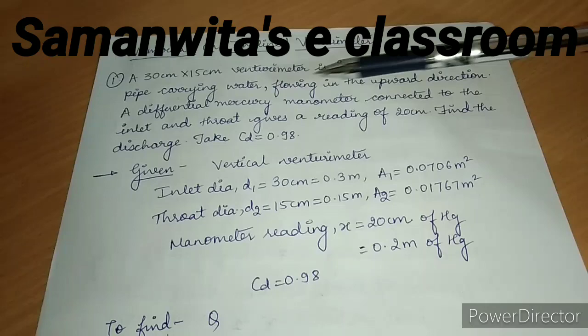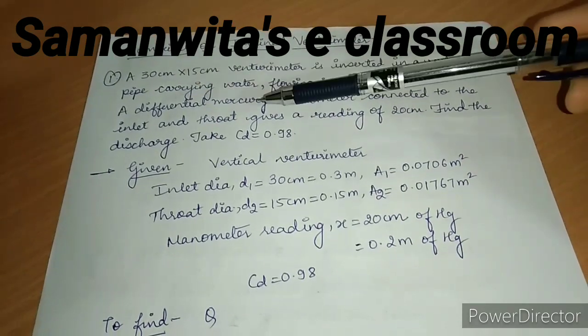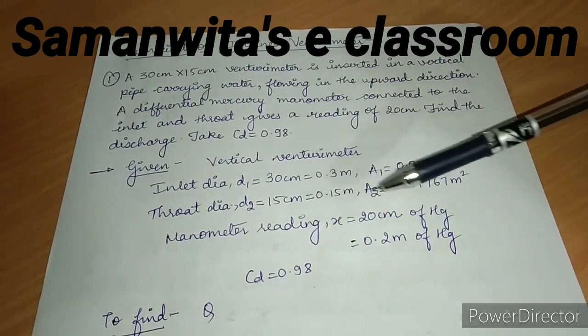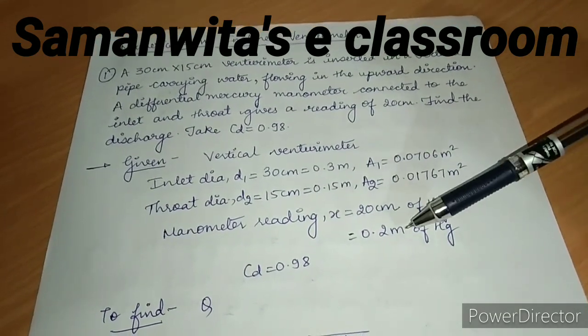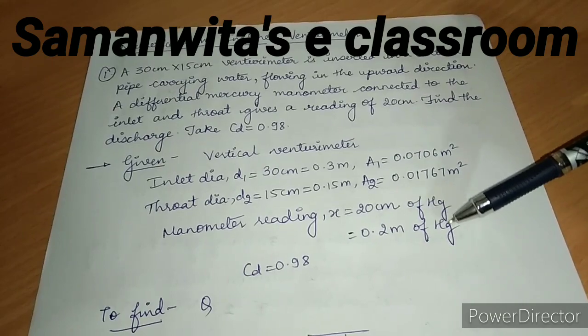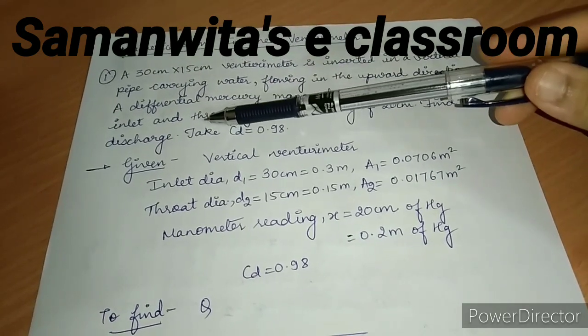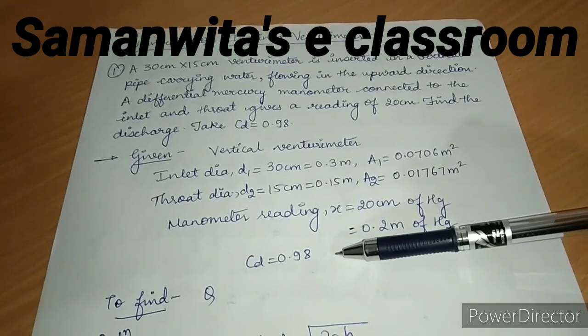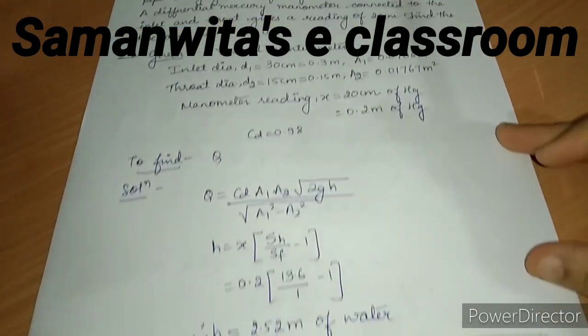The differential mercury manometer connected to the inlet and throat gives a reading of 20 centimeter, which means the manometer reading X is given as 20 centimeter of mercury. I converted it into 0.2 meter of mercury. Find the discharge, which means I have to find the value of Q, and the CD value is given to me as 0.98.